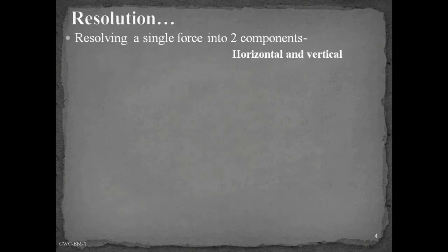The first step is the resolution of forces. It is the process of splitting up the given force into a number of components without changing its effect on the body. As a usual practice, we resolve the force into two mutually perpendicular directions, that is, we get horizontal and vertical components. Since the given forces act in different directions, we can't simply add them all together to get a single resultant force. So first we are trying to resolve each force into its horizontal and vertical components.